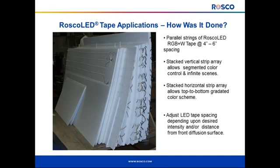Likewise, we had a series of the LED tapes strung in a horizontal array, which allowed the top to bottom gradated color scheme. One important point to mention is that the spacing of the tape is very much dependent on how much distance you have from that tape and backer board to your front diffusion surface. So it's very easy to make adjustments to get that nice uniform lighting and to achieve the exact effect you're looking for.